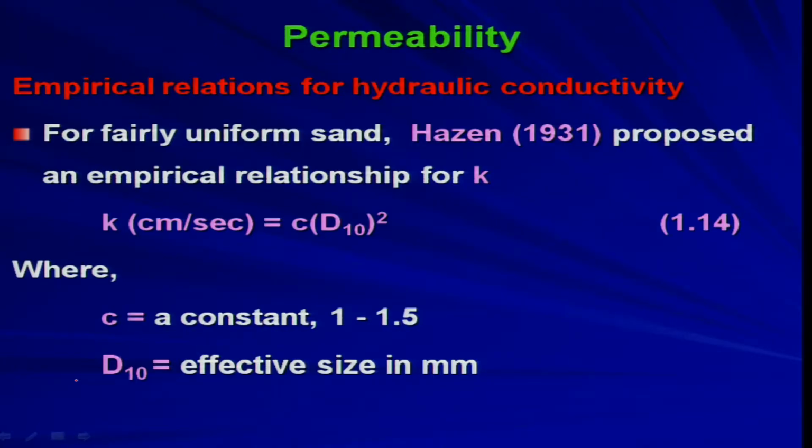So, please remember the unit because this is an empirical equation. D10 is expressed in millimeter, whereas k is expressed in centimeter per second and C is a constant.